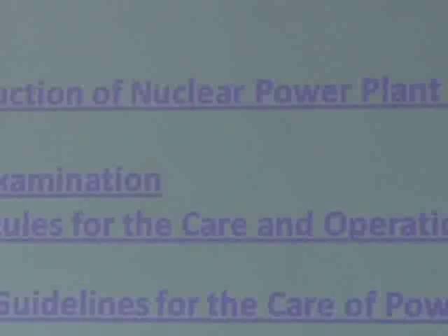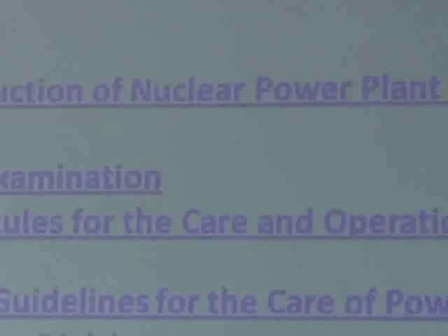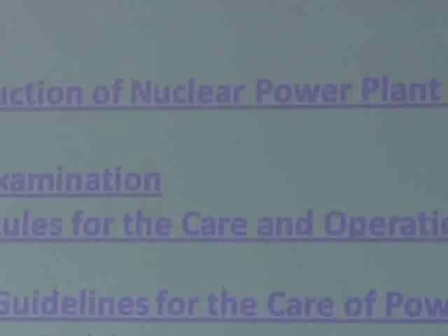If we're looking here, there's section 9 on welding and brazing qualifications, for example. So it will tell you what kind of procedure you need to do for almost each new project or each new geometry to determine if such welder and such procedure can be used for your design. So it's relatively prescriptive. One of the reasons is, to some extent, that with pressure vessels there's a safety risk associated with a failure, and I think that's a little bit why it's regulated in such a way.